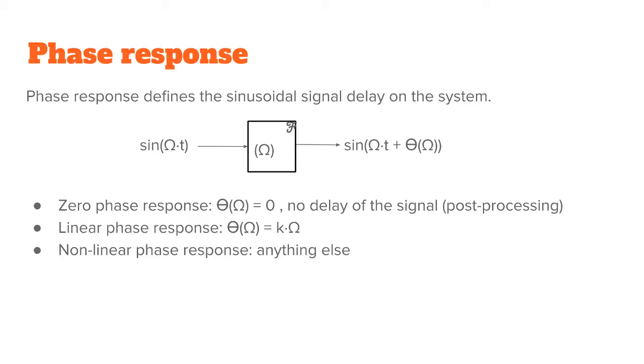3 different cases. On analog systems, you have only one case. It's always nonlinear phase response. You can get a near approximation, the minimum nonlinearity on the phase response would be on Bessel filter. Okay, but in digital filters, we really have three different cases. Linear phase response, meaning that the phase response can be described as a constant times the phase angle.